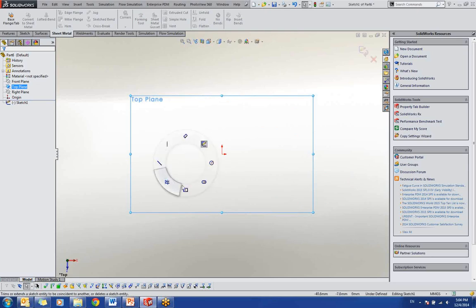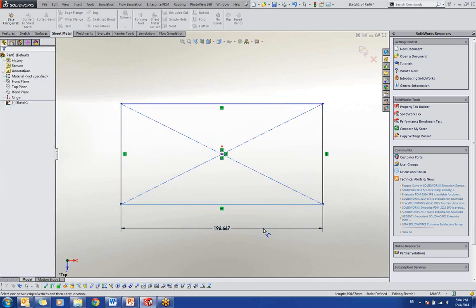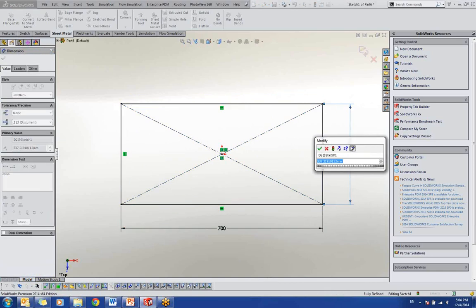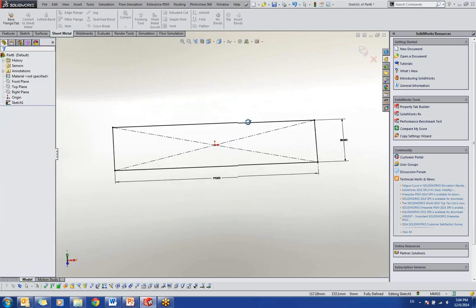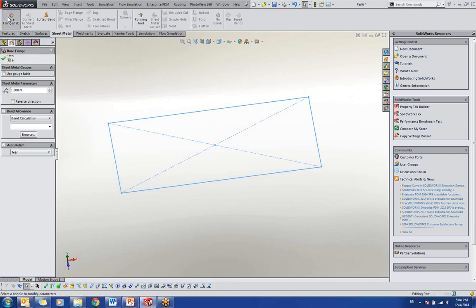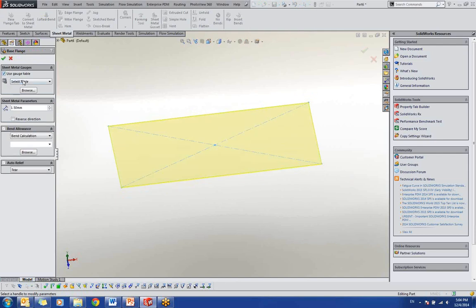And then I just build a normal rectangle first with the length of 700, and the height and the width I'll give it 300. Okay, it seems it's already done. For the sketch, if I'm using the normal practice, I have to make a very thin profile and then extrude it. By using sheet metal, I just use this one. The Sheet Metal tab has a base flange or tab. It auto detects the square, and then I can use the gauge tables.